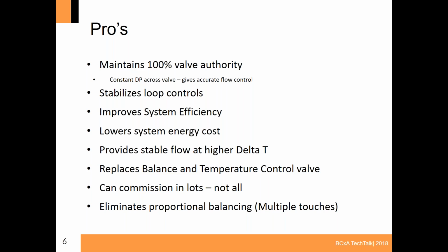Another one for the commissioning side of things is you can commission in lots, okay? Not balance and commission the entire system, right? If I balance a little system that's got 3 valves, those things are balanced. I don't need to come back and worry about rebalancing those items. I can move on to another group of control valves and make sure that they're set and getting the proper GPM, and then move on to the next, right? I don't have to keep coming back, like per the ASHRAE standard, touching that balance valve 3 times and making it work properly.